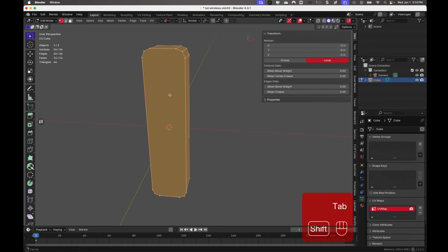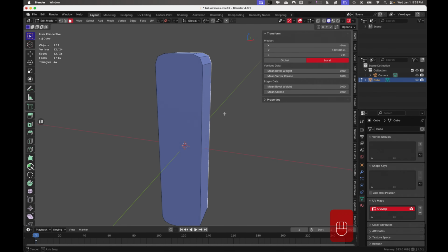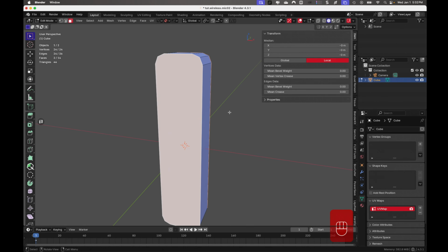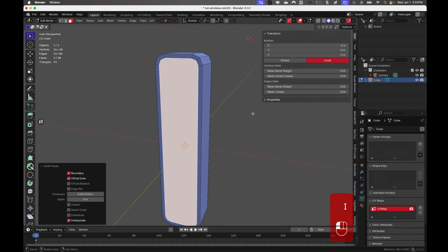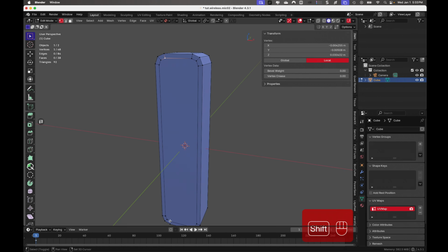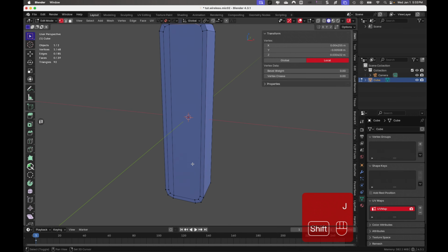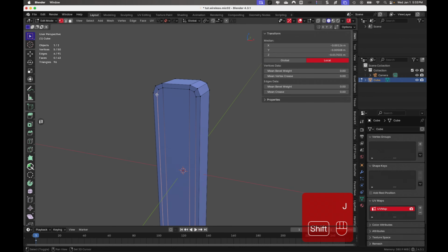And then once we come here, I'm going to select the two faces. Might help if I hit the right key. I'll inset, vertex mode, and then what I want to do from here is start cleaning up the geometry a little bit, just so we don't have weird n-gons here. And it's pretty simple stuff that we're doing thus far.